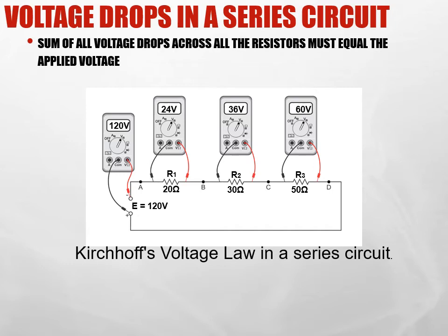Now when we look at voltage, we can use something that's called Kirchhoff's voltage law. Kirchhoff noted that the individual voltage drops across each resistor will add up to the power supply, or the voltage around any one current loop is equal to 0, is how he actually stated it. So that the total voltage is equal to the individual voltages within the circuit.